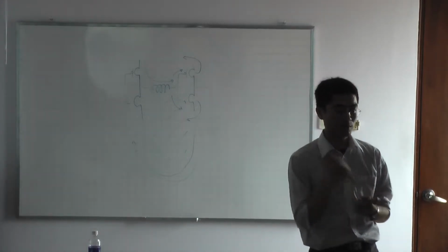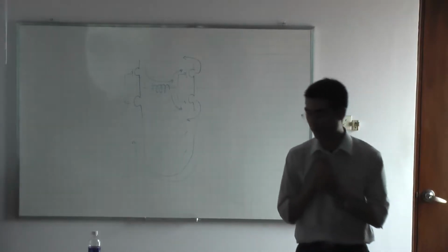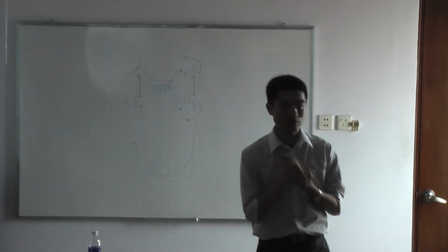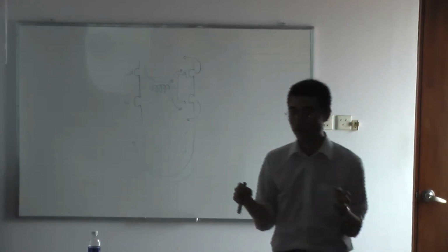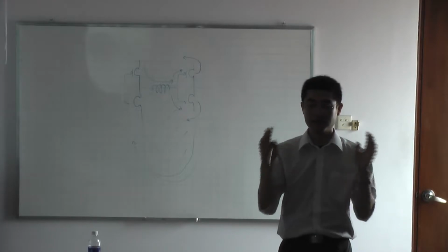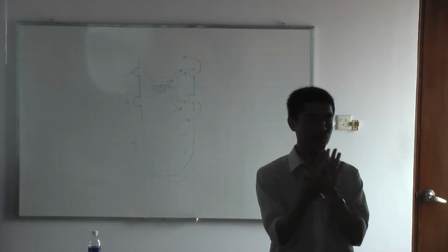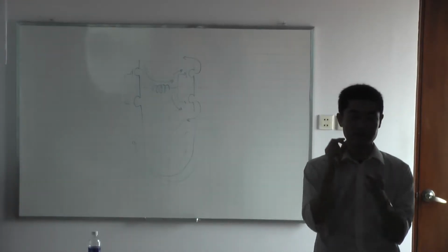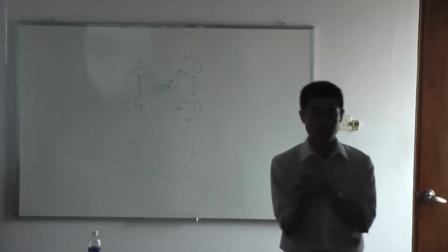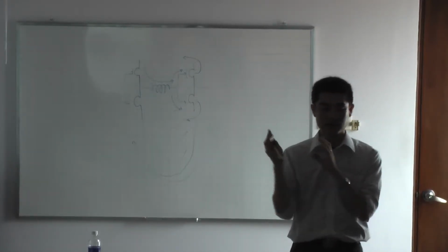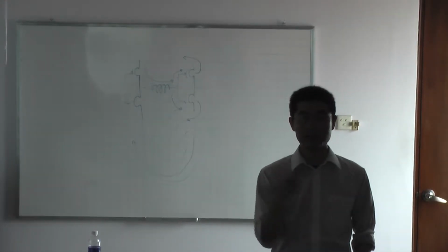And another one is a blocking capacitor. This is also often used. The blocking capacitor is just a large capacitor. For large capacitors, the impedance becomes 0 for AC signals, and the impedance becomes infinity for DC signals. So the blocking capacitor cuts off all the DC component and passes through the AC component. That's a blocking capacitor.